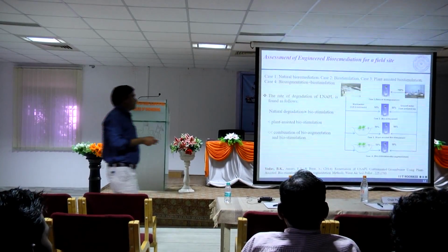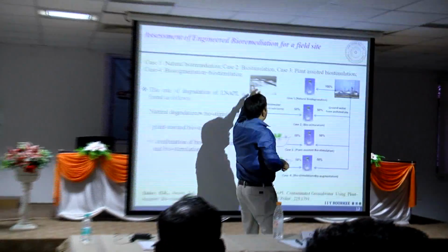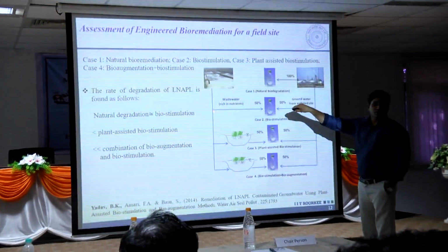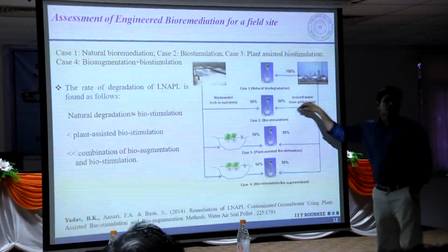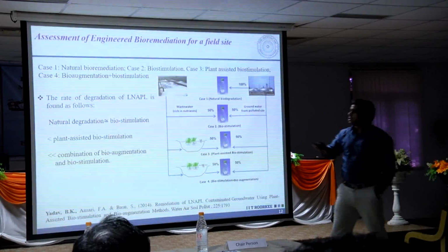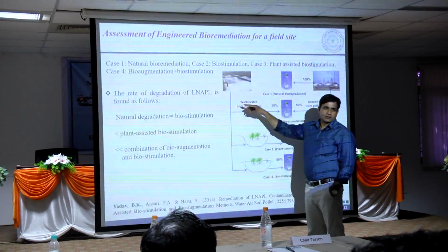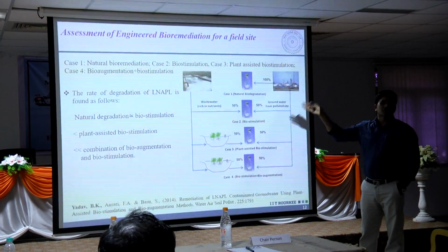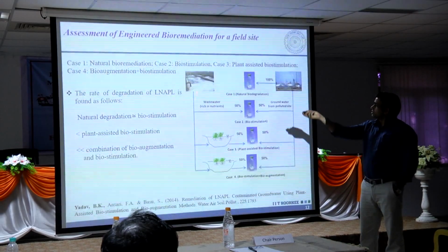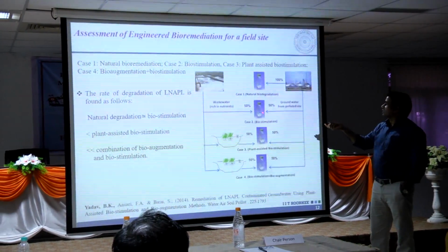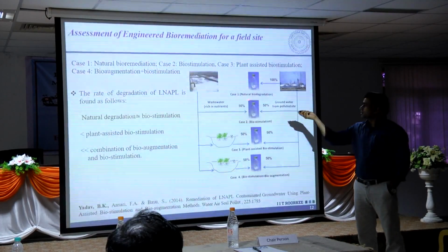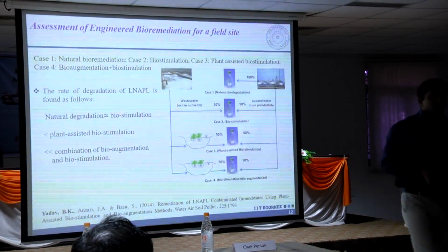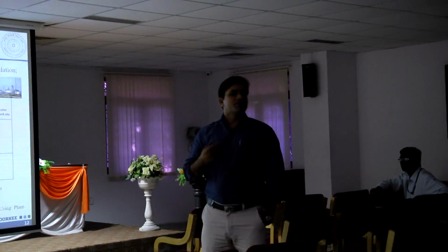So we collected the wastewater from our campus, which is wastewater coming from the households, and the groundwater, in a 1:1 ratio. It means nutrients have been supplied from the wastewater. Actually this is not just a wastewater, but a naturally nutrient-rich resource. So nutrients are coming from here and the polluted groundwater is coming from here. So that is going to be a type of biostimulation. Biostimulation will provide the extra supplements so that the microbes can work more efficiently.